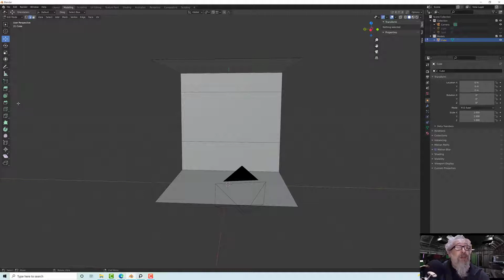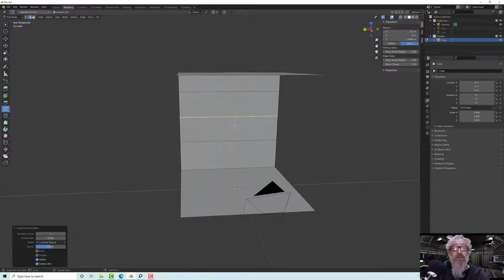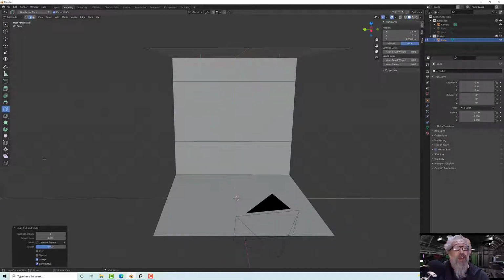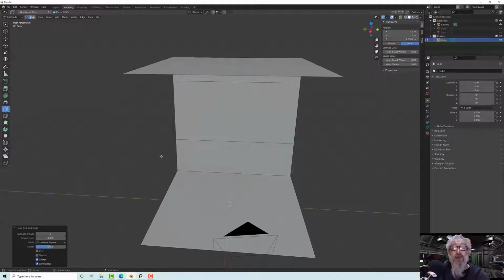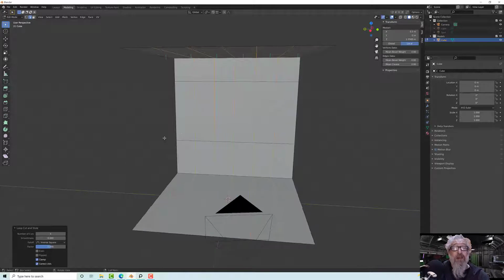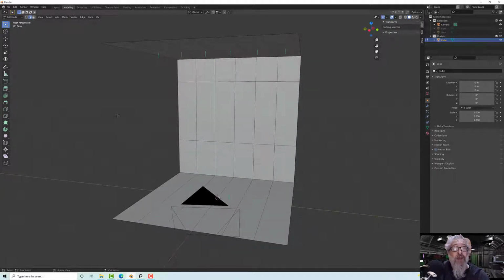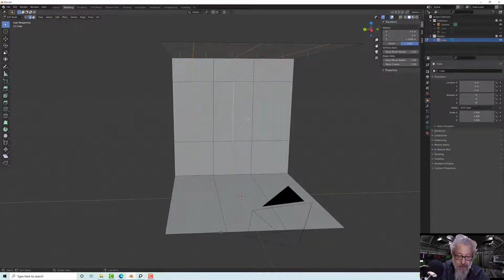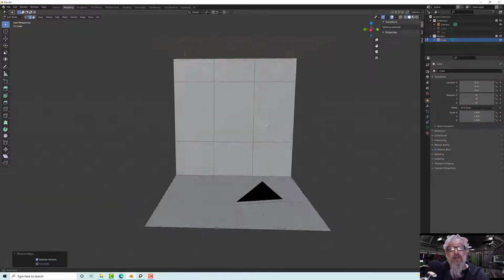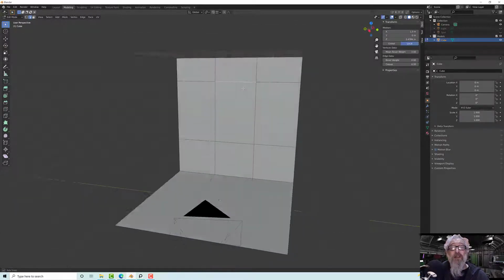So let's put the verticals in. So I'm going to click loop cut and cut down the middle, and then I'm going to increase my number of cuts here to around 5. Now I'm not going to keep all these, it's just getting me an approximation. So let's go back to select mode and just click off to deselect. Then I'm going to alt click and then shift alt click on these two and the one down the middle, and then delete and dissolve those edges. And now I've got a size in here.